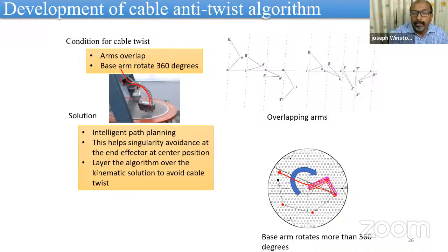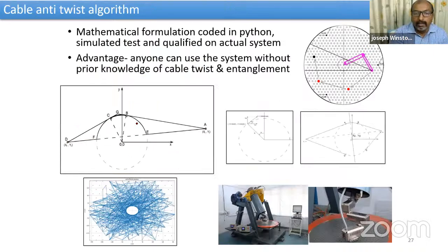So we thought of a simple mathematical way. What we did was evolve a virtual circle at the center, and never allow the end tip to pass through this virtual circle. Whenever the operator is standing at point A and has to go to point D, it draws a tangent to this virtual circle, finds this point, goes along the curvature, exits on a tangent from this, and then goes out. There are two possible ways. Here also you will get a tangent. This is also possible. But we find the length of each, and to reduce the duty cycle, we choose the lesser path and go through this.